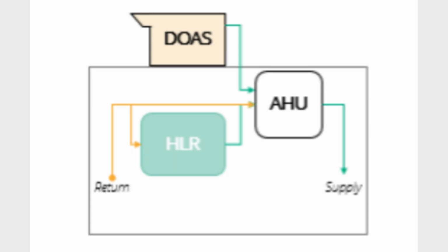Practical HVAC applications of psychrometric charts. Determine entering and leaving coil conditions. Balance sensible and latent loads. Select proper supply air temperature and airflow. Evaluate coil capacity and system behavior under variable load. Essential for design of AHUs, DOAS, and control sequences.